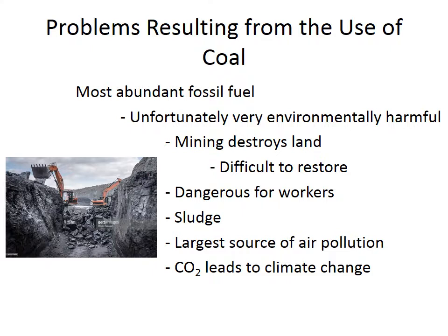Mining does produce coal, but it also produces a byproduct called sludge. And that sludge is pollutants that are collected. They're held in ponds. The water becomes very, very toxic where it is. The water should evaporate out, leaving behind a more concentrated sludge over time. If this is an area with a water table aquifer where the water is right underneath and there's no cap between it, the toxins can start to seep into the groundwater, which can then contaminate wells. There have been instances where these sludge ponds have ruptured or overflowed that has caused serious water pollution.